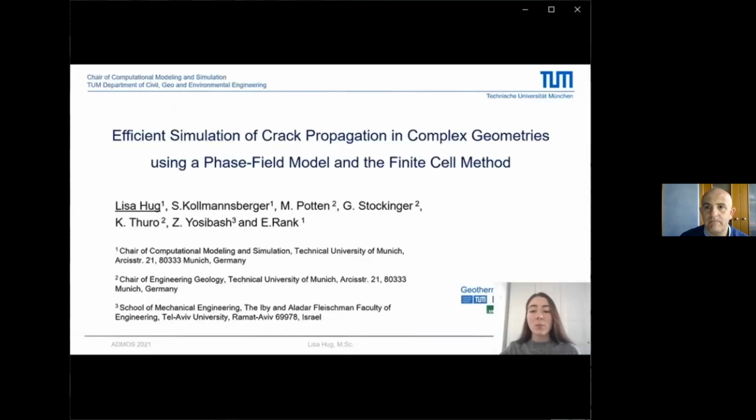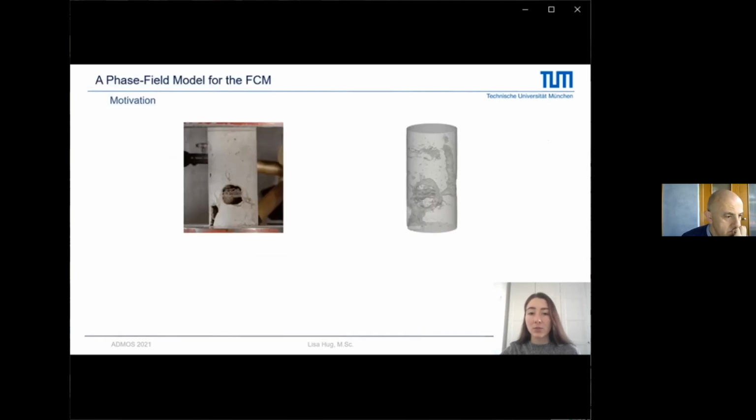Hello everyone, my name is Lisa Hook and I want to give you a short overview of my talk, Efficient Simulation of Crack Propagation in Complex Geometries using a phase field model and the finite cell method. I will talk about how a phase field model can be combined with an embedded domain technique and adaptive refinement, and which additional ingredients are necessary towards an efficient simulation of real-world crack scenarios.